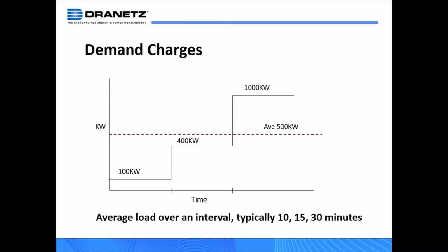put on a tier. So for example, let's say your highest demand interval for the month might have been 100 kW. Well, then your pricing might be somewhere along the lines of $7 per kW. I'm just throwing numbers out there. But let's say from 100 to 500, and your demand falls within that window, then the price per kW will go up. And so the higher your demand is, the higher your price per kW would be. So that's basically how the utilities derive your demand charge on your bill.